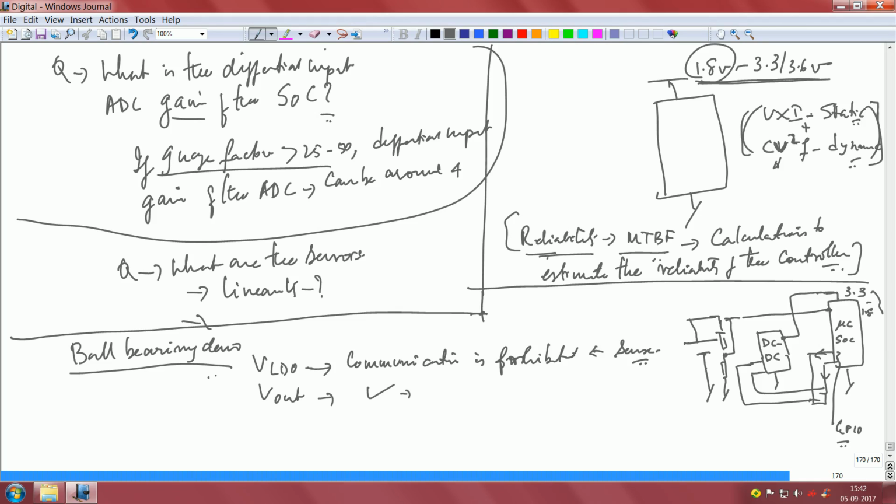This is coming from here and input perhaps goes here. This is important. Put two resistors R1 and R2, a simple resistor divider network, sense it and use that for taking an intelligent decision. You should be able to write nice software code, which is possible, but the controller itself should be able to work in this range, 1.8 volts to 3.3, and that is a very important requirement.